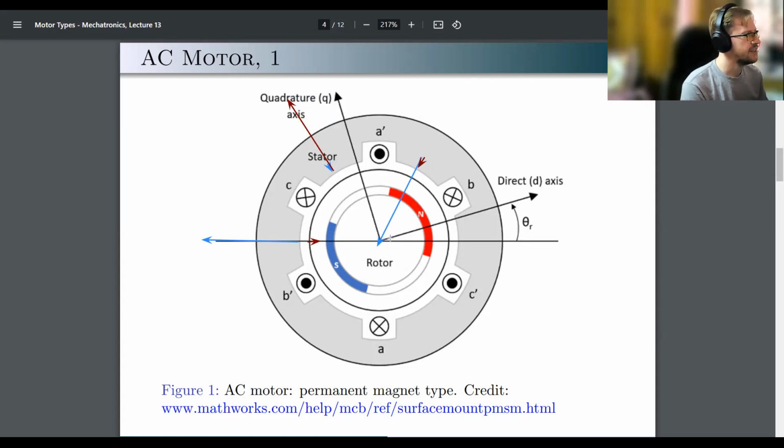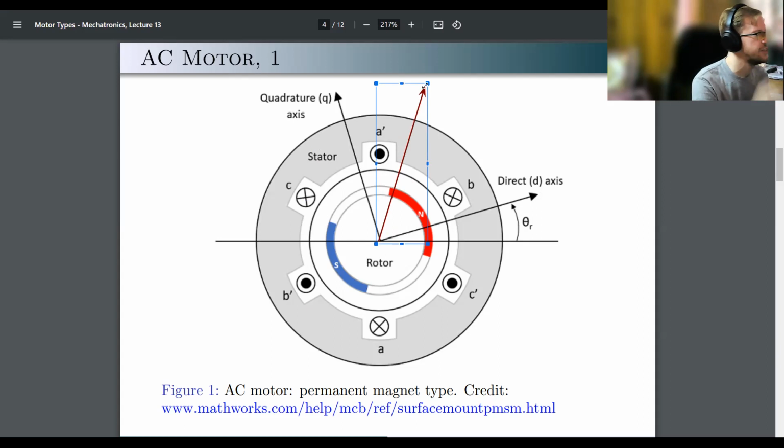The idea is that as your motor moves along, your three-phase electricity will also move along, rotating the overall magnetic field. And that is a common idea in describing these types of motors. So what we say is something like this. The cumulative magnetic field, if you sum all the magnetic fields produced by individual motors, rotates. So let's say your magnetic field currently is facing this way. So I sum all three magnetic fields and I say, okay, it faces this way.